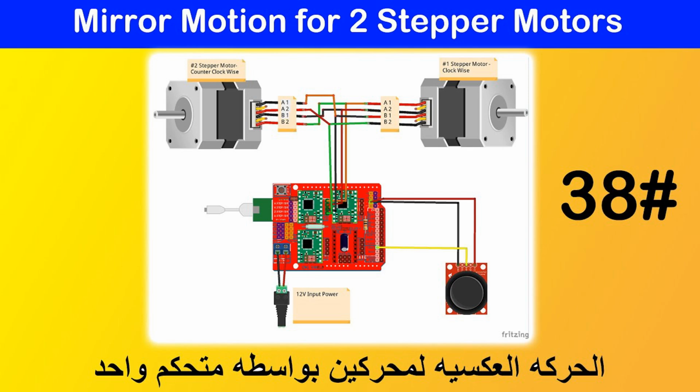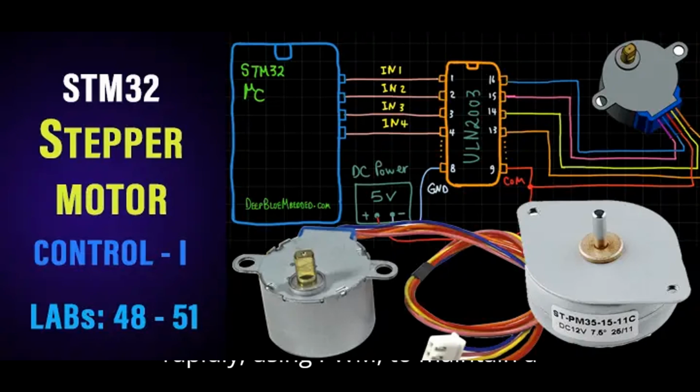5. Chopper stepper motor drivers. Function: these drivers regulate current to the stepper motor in a chopping manner, which helps to keep the current constant through each coil. Operation: the chopper refers to the driver's ability to turn the current on and off rapidly using PWM to maintain a constant current through the motor windings, ensuring efficient operation and reducing overheating.